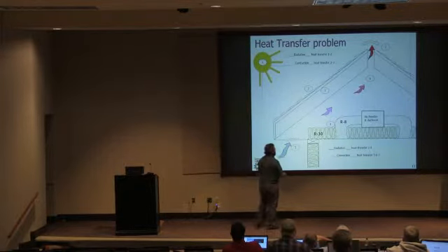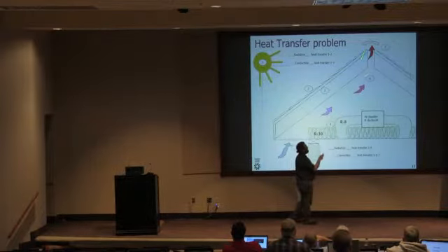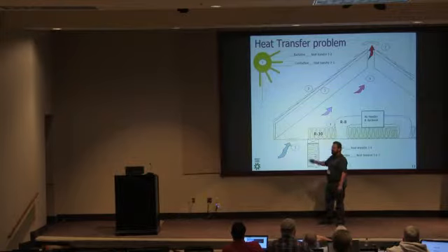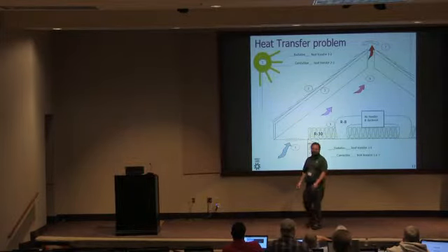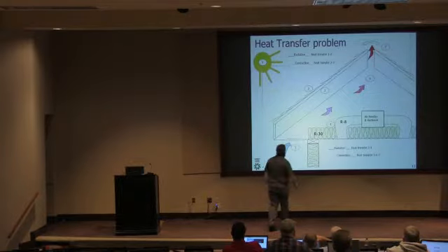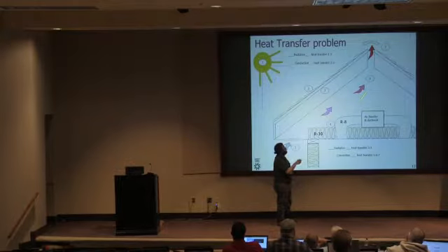And then what do we do? We use convection to try and cool that roof with venting, right? Hot air goes out the top. It's made up by cooler air coming in the soffit vent here at the bottom. So in the summer, we're sending 125 degree air out the ridge vent, and we're bringing 90 degree air in through the soffit vent. And that's the idea, that we're trying to cool that roof with the natural force of